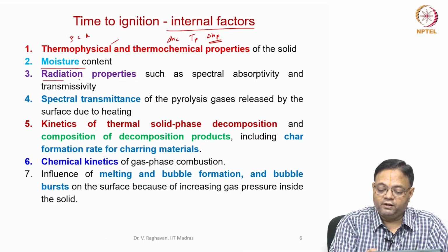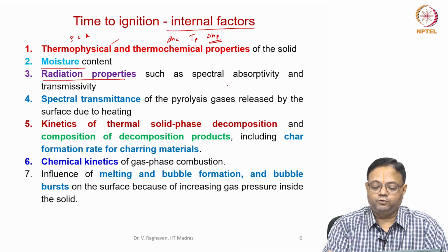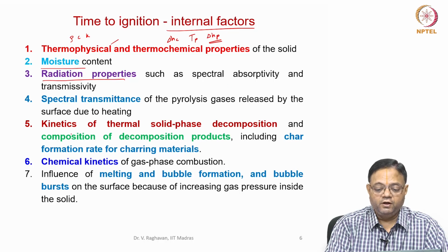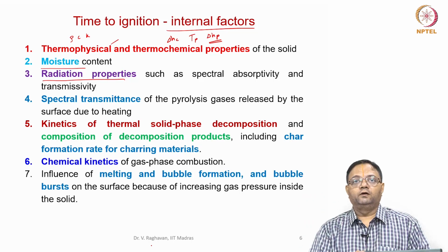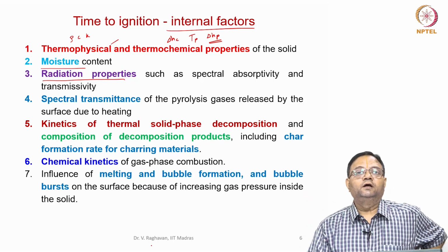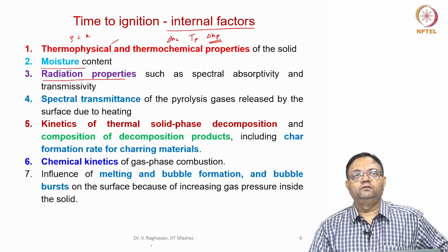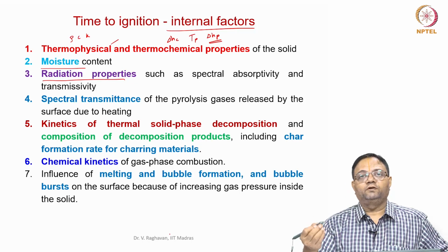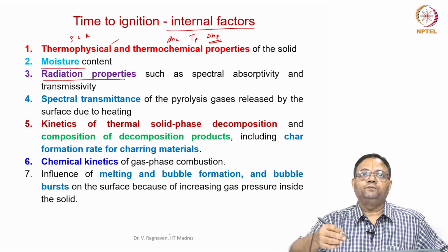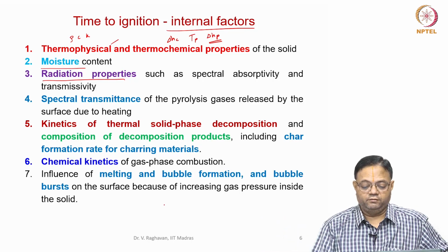Then radiation properties, as we have already seen: surface absorptivity, transmittivity, etc. of the solid surface. Because if there is a radiation loss from the surface to the ambient, that will increase the time to ignition. When there is a heat loss from the surface to the ambient, then the time to ignition will increase. Then